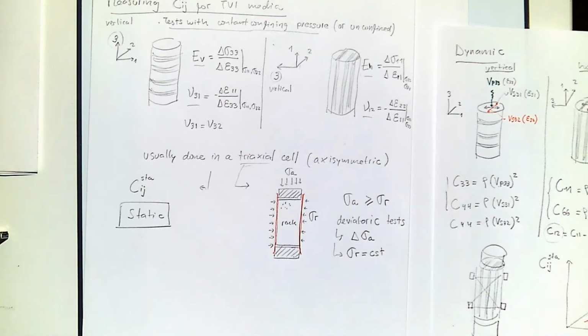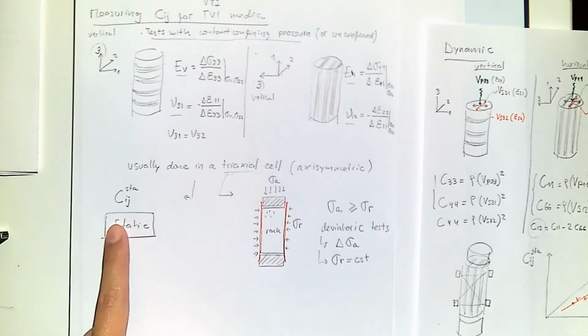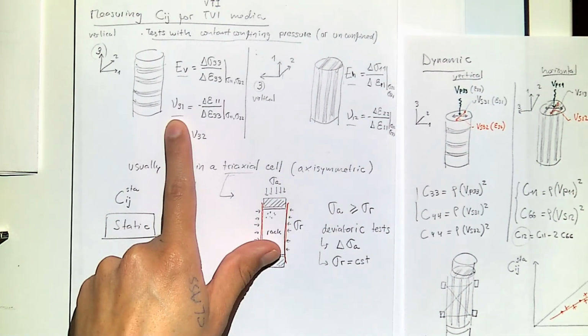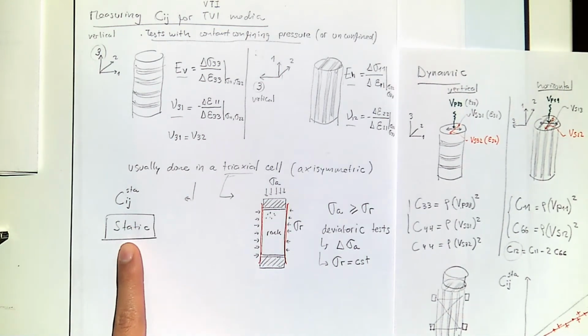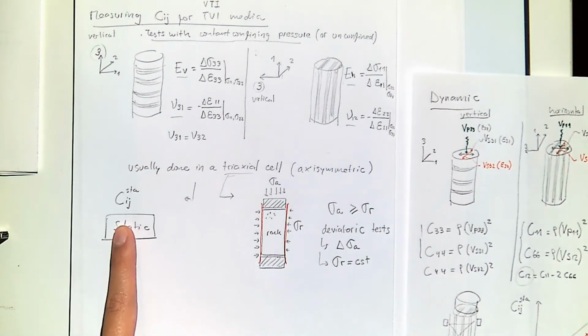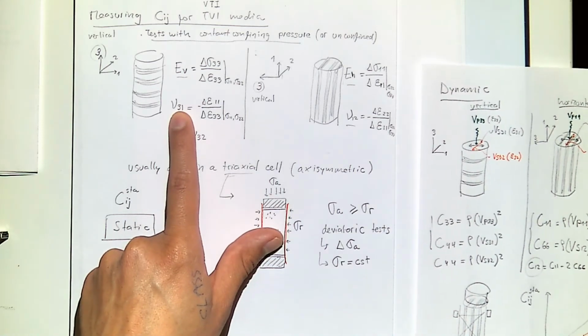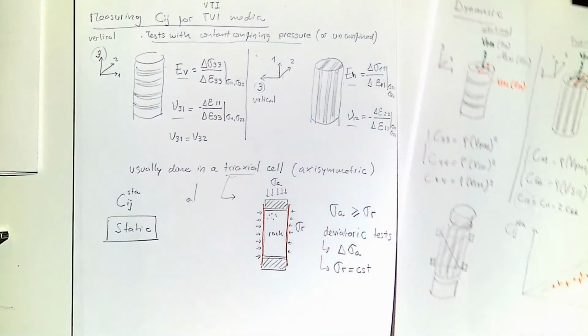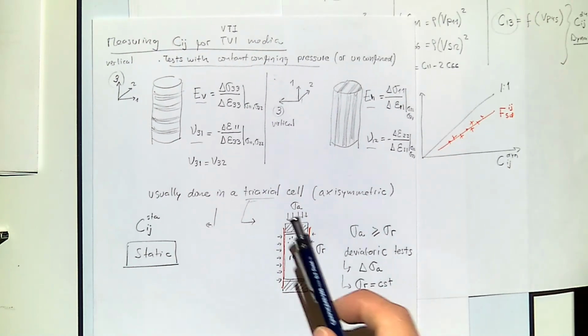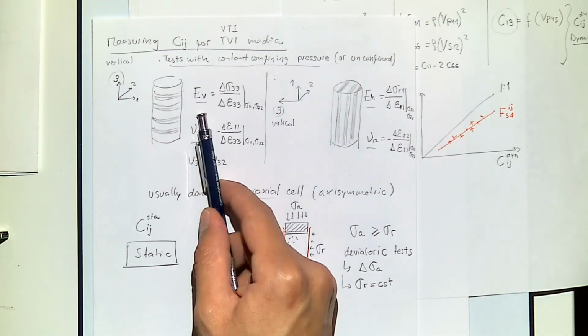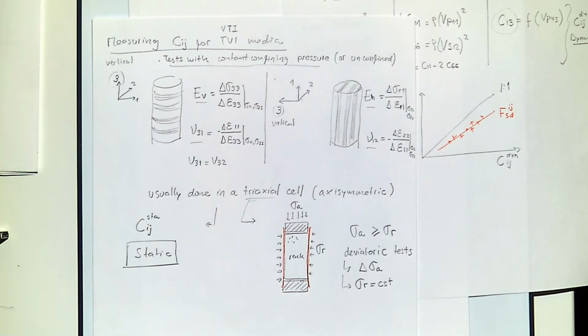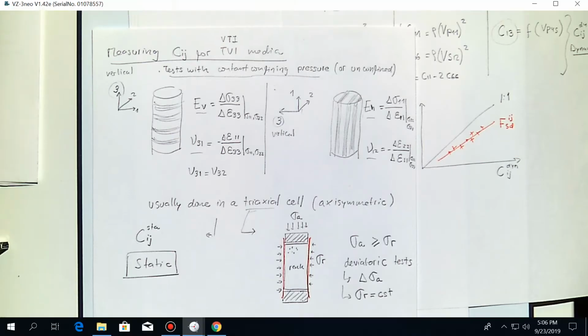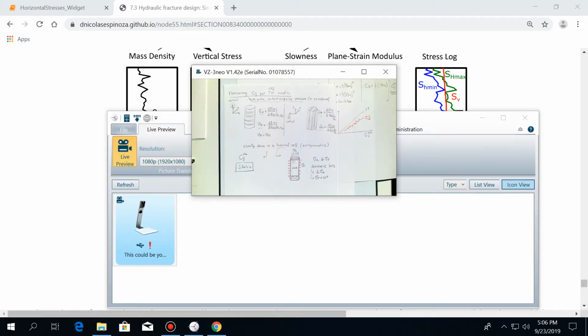And thank you for that question, because I didn't clarify how to get from here to there, right? So these are stiffness coefficients, and these are Young moduli and Poisson ratio. So in order to get from Young moduli to Cij's, you have to use some equations. And let's see if I have them here. I don't think I do, so I'm going to have to pull up that paper quickly.